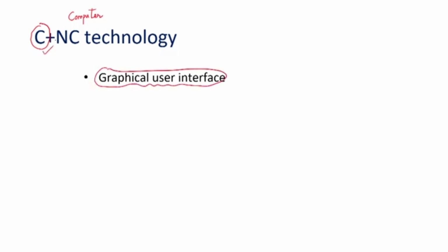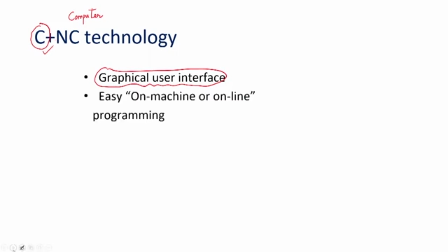Moreover, the CNC machine tool is also helping us to provide various auxiliary functions such as automatic tool changing. So, automatic tool changing is possible nowadays. Then the pallet changing. So, pallets are nothing but the platform over which the work parts are arranged in arrays, and these pallets are fed to the machine tool. The tools are coming, the lasers are coming, and they are processing the work parts in one go.